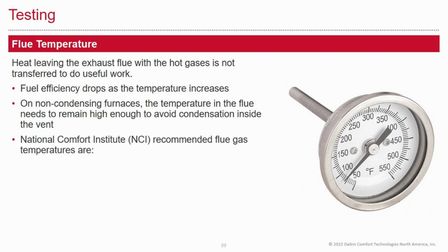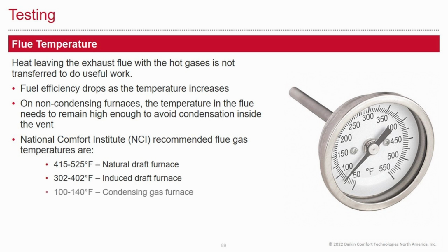The National Comfort Institute recommended flue gas temperatures are 415 to 525 degrees Fahrenheit for natural draft furnaces, 302 to 402 degrees Fahrenheit for induced draft furnaces, and 100 to 140 degrees Fahrenheit for condensing gas furnaces.